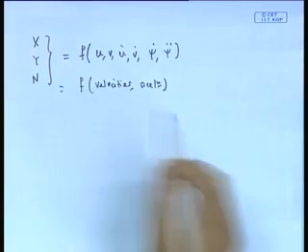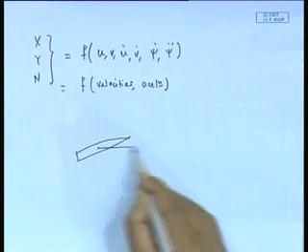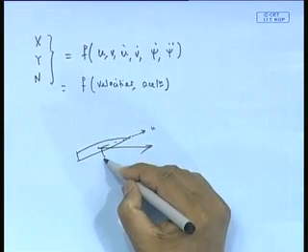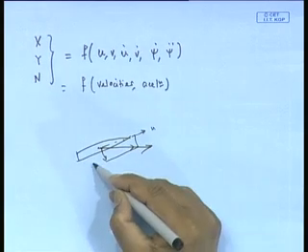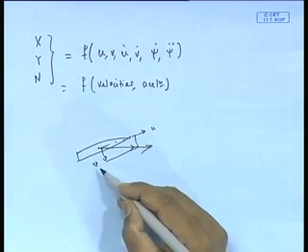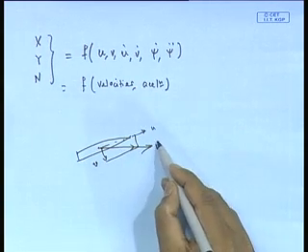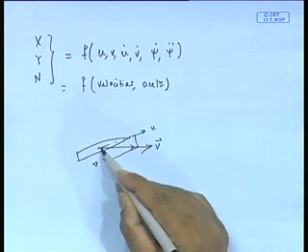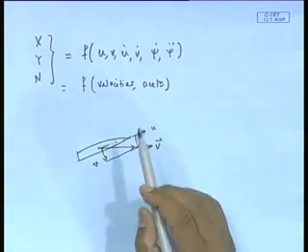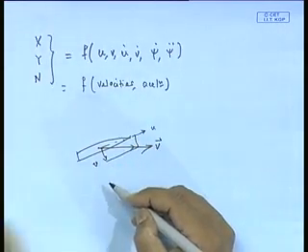So, if I have for example v, what is v? An angle of attack. Remember that if the ship is going along this side with this u, then obviously I am having a small v, because remember this is my vector. Non-zero v means what? Having an angle of attack, because only when it is going this way, u is along x axis, v will be along this axis, and this is the vector. So obviously non-zero v means it is going with an angle of attack, and now of course it may be having an acceleration on this side, sway.